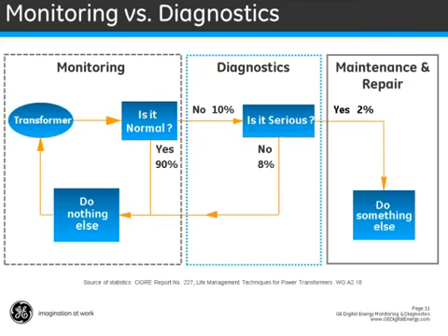For example, if we look at offline bushing testing, it is generally carried out every 3 to 5 years and sometimes longer. They are typically completed by a third-party company, and tests are done at lowered voltages and under very different temperature conditions due to the absence of load. Under these circumstances, any quickly progressing problem would be missed and could result in serious consequences.